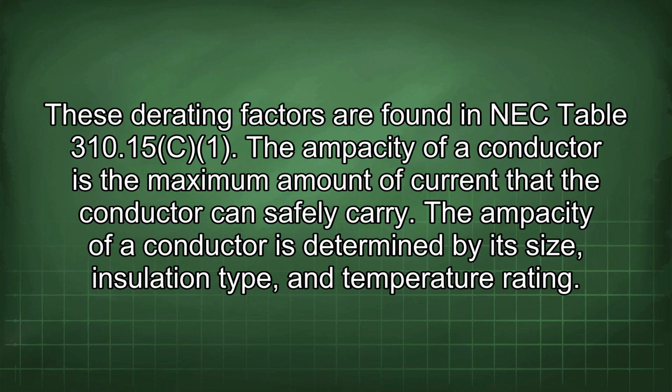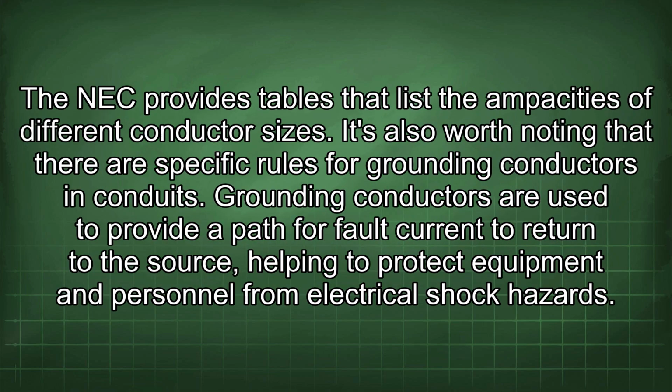The ampacity of a conductor is the maximum amount of current that the conductor can safely carry. The ampacity of a conductor is determined by its size, insulation type, and temperature rating. The NEC provides tables that list the ampacities of different conductor sizes.